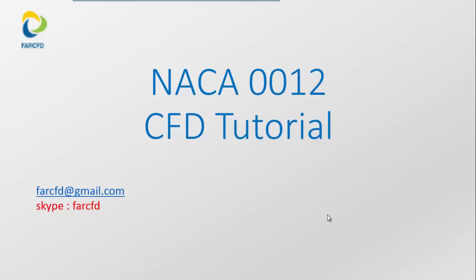Hello everyone, good evening. Today we are going to learn how to simulate the NACA 0012 aerofoil, or any other type of aerofoil, in the Fluent software. So we'll start with getting the coordinates of this aerofoil, and then we will import them to the Design Modeler.